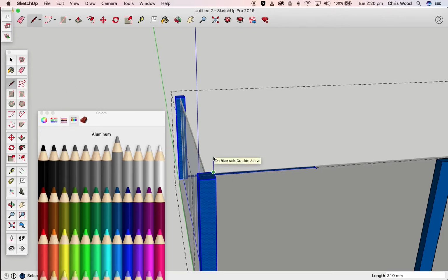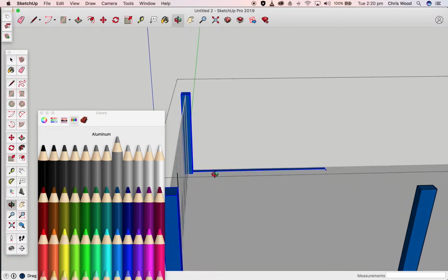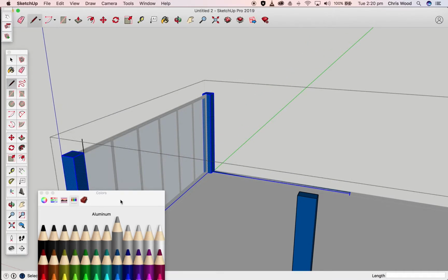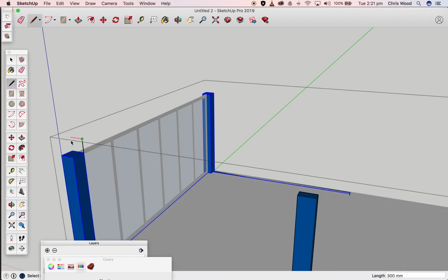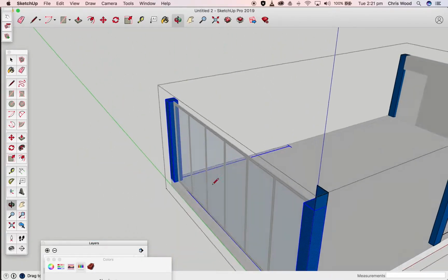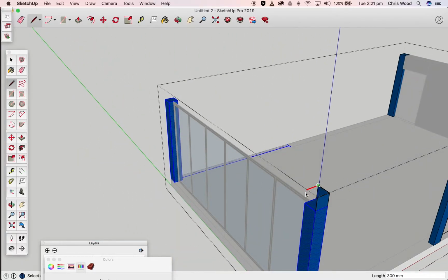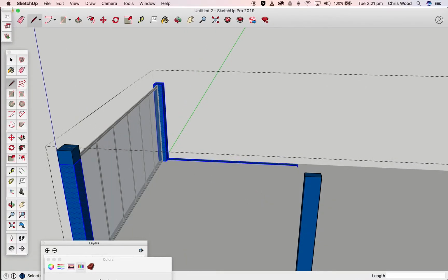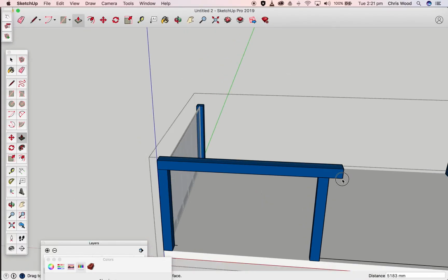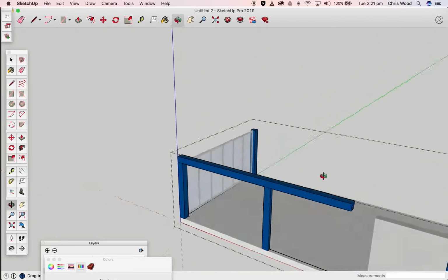So I'm going to come up, I'll keep this quite cubic, so I'm going to come up 300, and I'm just going to come across. I'll just get my colours out of the road there. There's different ways of doing this, but it's just the way I like to do it. I kind of like just filling stuff in with the pencil as I go. And auto infer down and just fill it all in. That's good. Okay, so then I can just take that and I can bring it across as a single steel span, and I can keep coming along.